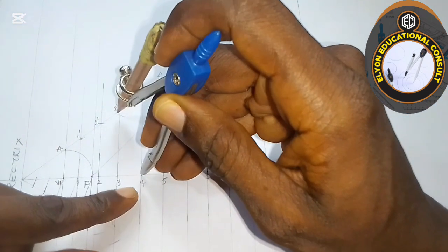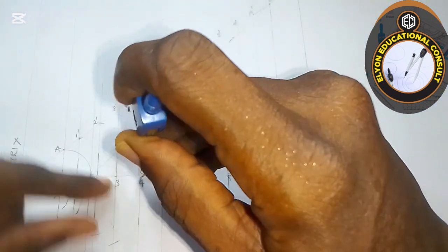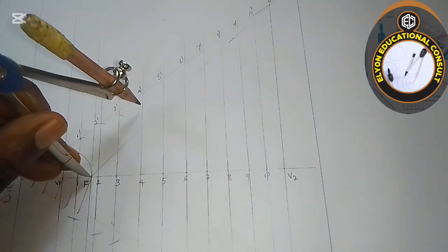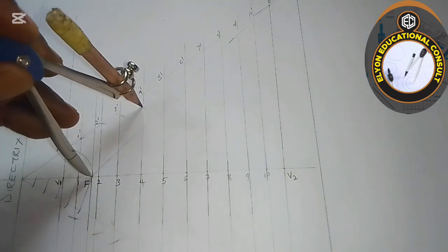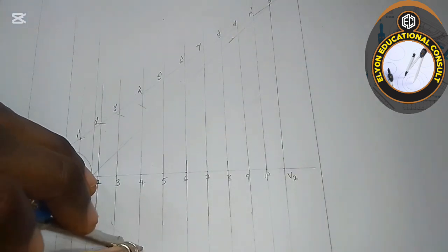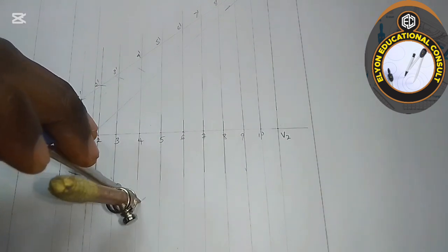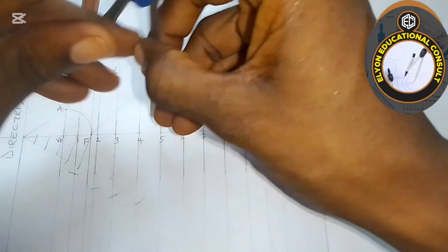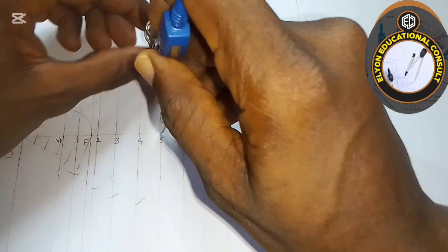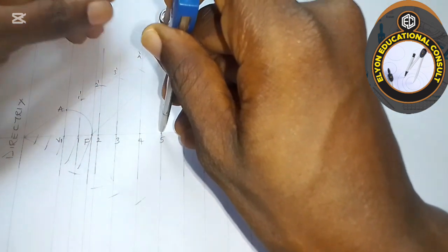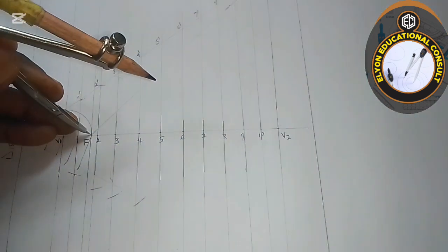So we'll be getting the ellipse drawn out that way with each of the points. Go back to the focus, always put at the focus. We have it this way, both up and down. Move it down so we can see that. Then we'll go to 5. We'll do that all across, then place on the focus.